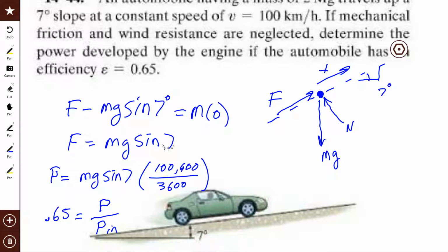Why? Well, for example, this is what goes from the engine into the car, but the car has some losses, then the car's not going to give me the output the same as what went in. It's got an efficiency. What does that mean? It won't go as fast up the hill. Because the power out would be this force times the speed. And if this is what goes in, and let's say you have a 50% efficient car because you've got friction in the bearings, rubber squashing, whatever it is, wind resistance, your kids have their hands out the window, that's causing an inefficiency.